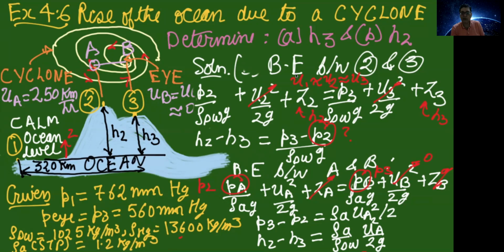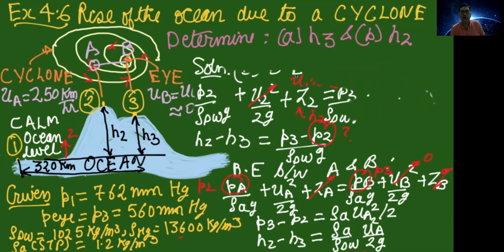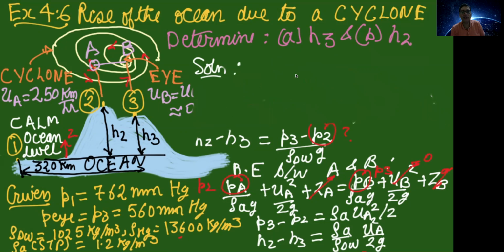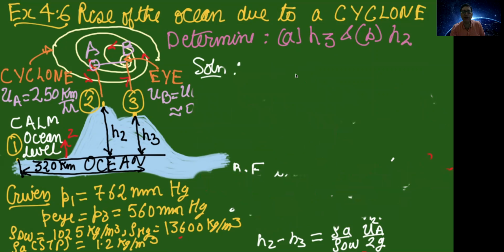Now, you are given the density of air at atmospheric pressure. However, we are applying it between A and B, and we know at B the pressure, we don't know the pressure at A. So from using the pressure at B, which is a subatmospheric pressure, first we will use ideal gas equation, where we are considering that the temperature is uniform between A and B.